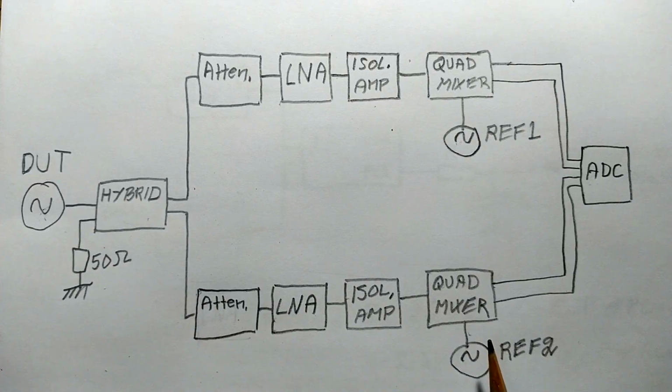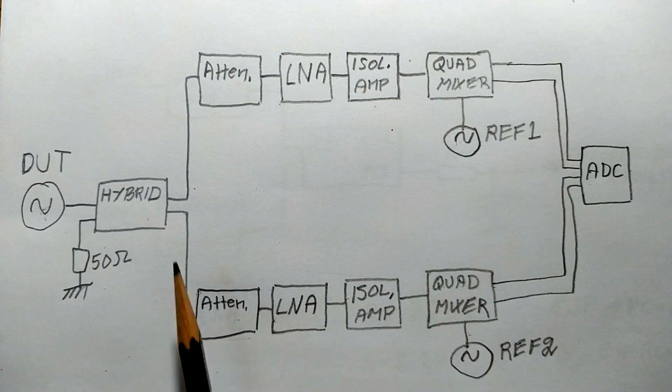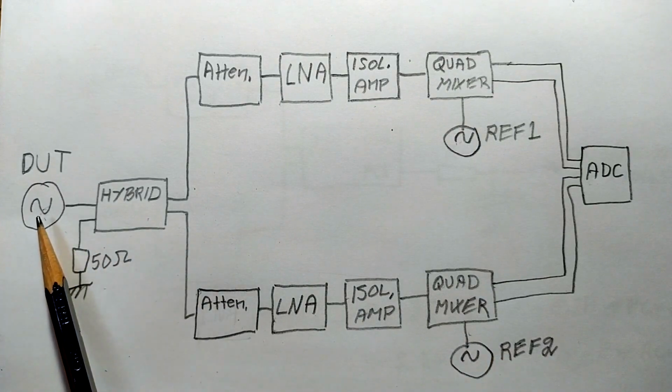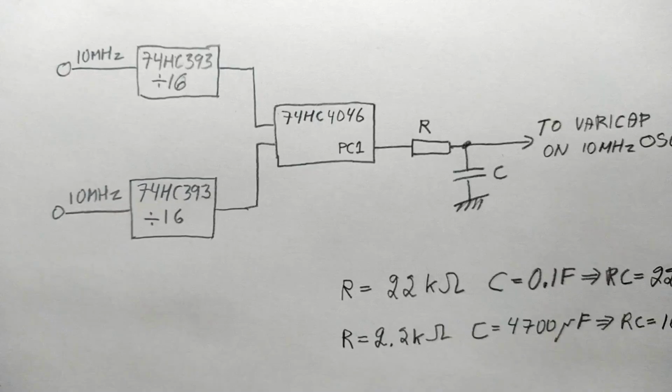And then with a slow phase lock time constant, they are independent in the short time scale, but in the long time scale, the average frequency has to be the same. Although it was drifting up and down a little bit, that's the same as this oscillator is also drifting a little bit up and down with time. So that is a normal phenomenon to handle in the software.